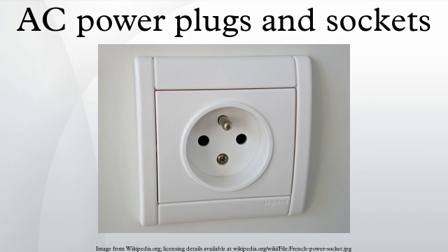Sockets used in kitchens, bathrooms and other wet areas are recessed, while those used elsewhere are not. Some plugs and adapters have a tapered form and can be used in either environment, while others will fit only the non-recessed sockets. Swiss sockets accept Swiss plugs or Europlugs. There is also a non-earthed 2-pin variant with the same pin shape, size, and spacing as the SEV 1011's line and neutral pins, but with a more flattened hexagonal form. It fits into Swiss sockets and Series 7/16 sockets, and is rated 10A.